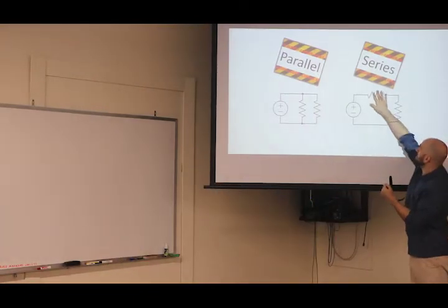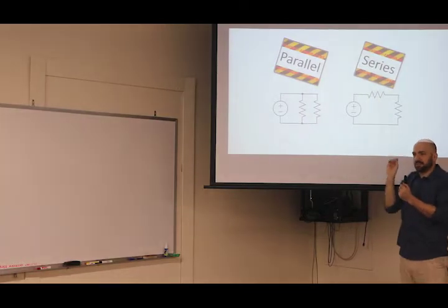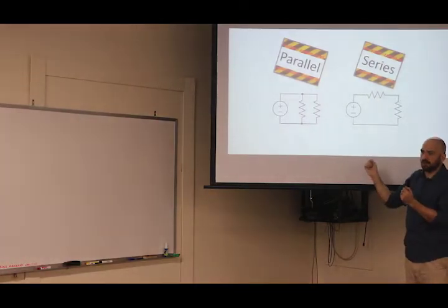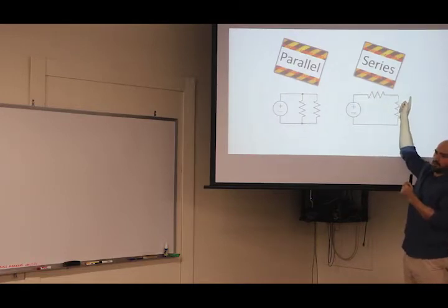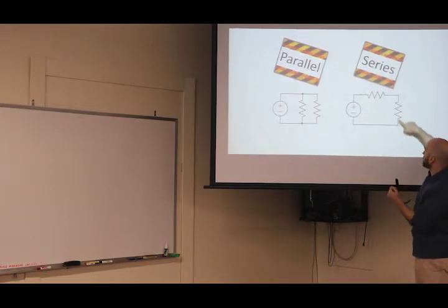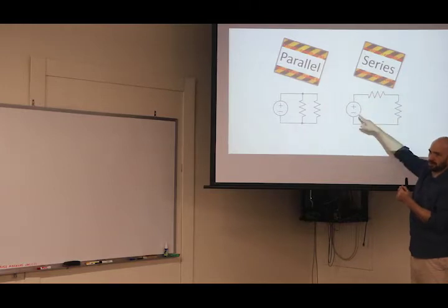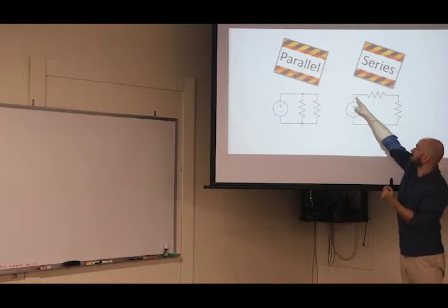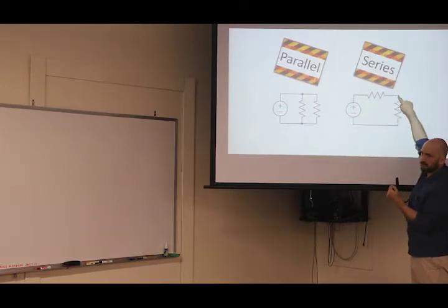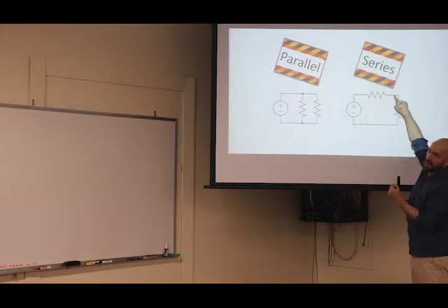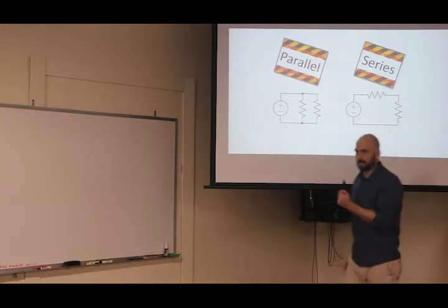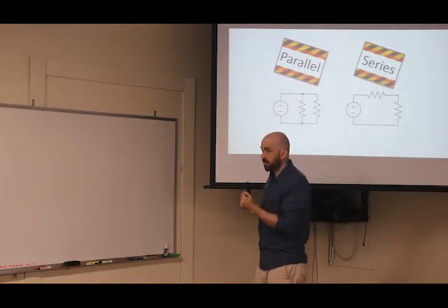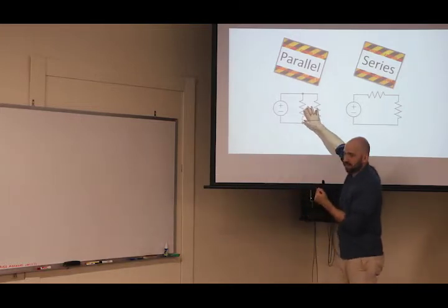So let's say this one is a tiny resistance, almost like just a plain wire. That means that there's going to be no drop across it, almost 0. And it's almost like you just had that one we showed earlier with 1 resistor and 1 here. So there's going to be very little and pretty much 9 here. 8.999 here and then 0. So all the voltage drop across the big resistor, very little across the little resistor. Both of these have 9, yes.